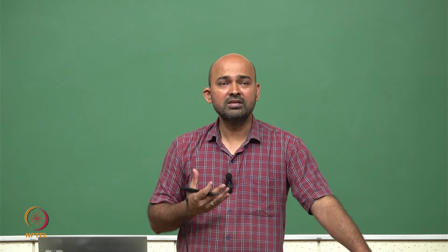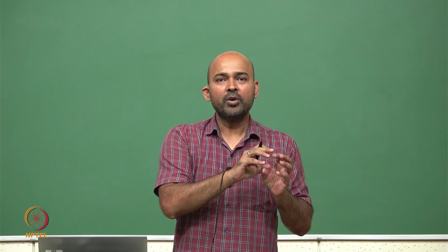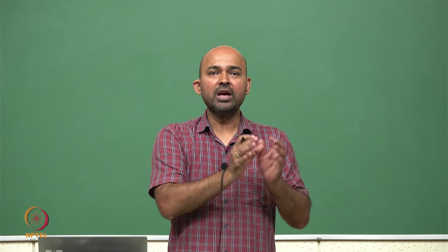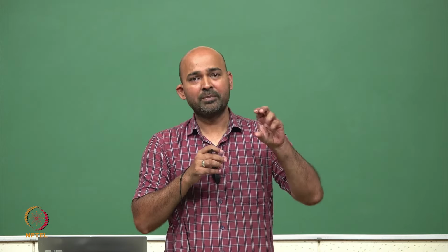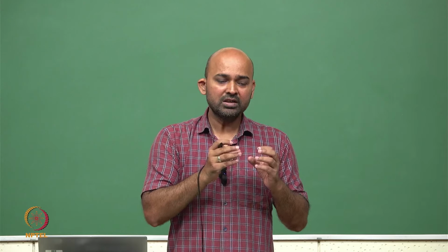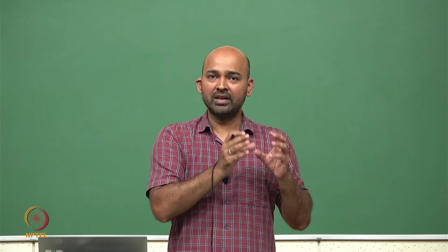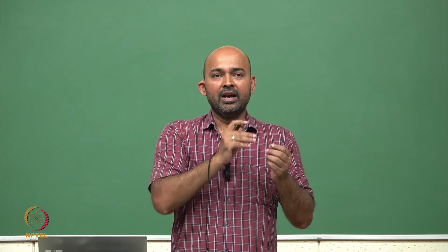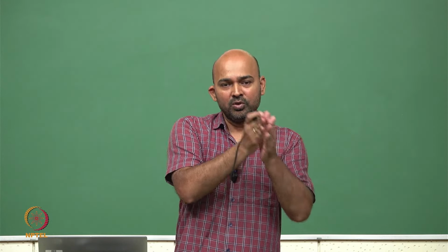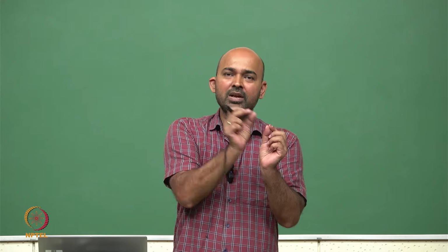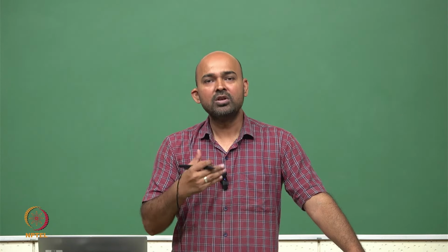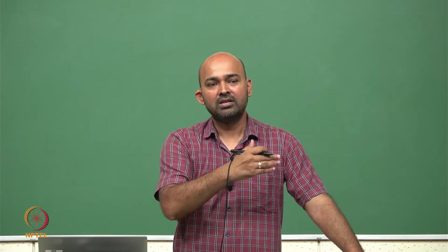In transient simulations, there is an operating point analysis first, which SPICE performs. Why do we do operating point? Because we want to know the initial conditions of the circuit. For example, if a capacitor is charged to some value, there is a charge storage, or the inductor has some amount of current flowing. Those are the initial conditions of the circuit at time t equal to 0. And then we apply a signal which starts right from t equal to 0 to the next instance, which is 0 plus delta t.